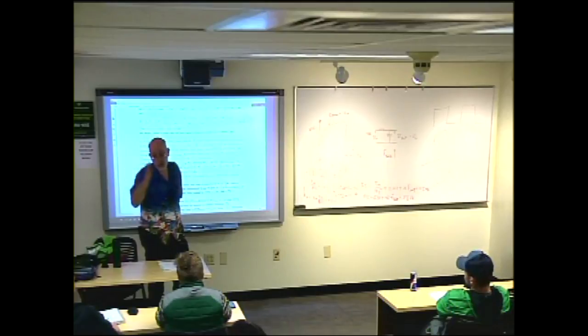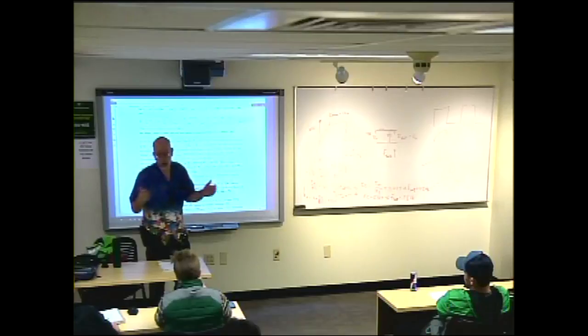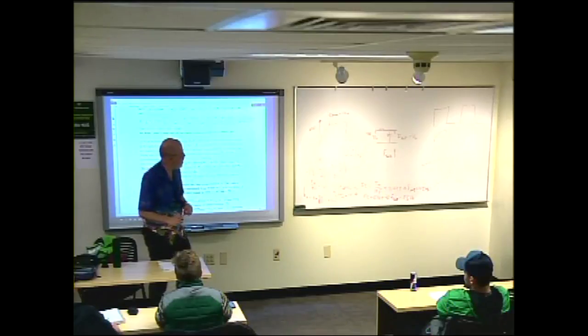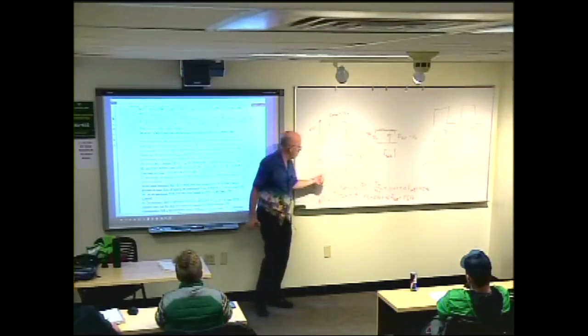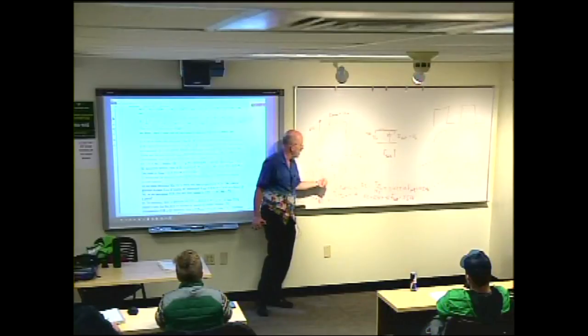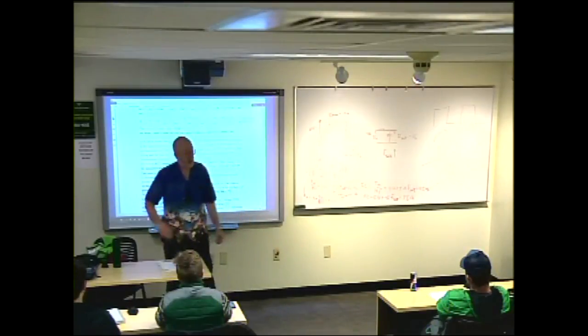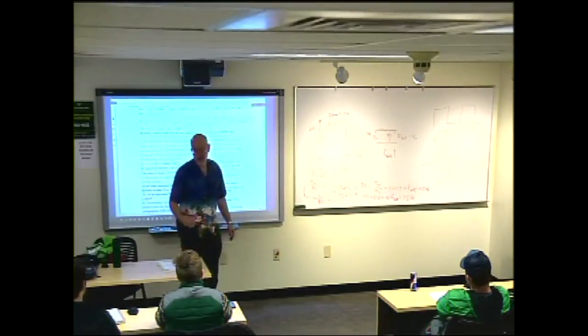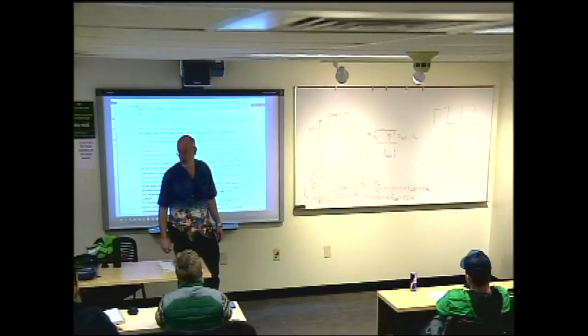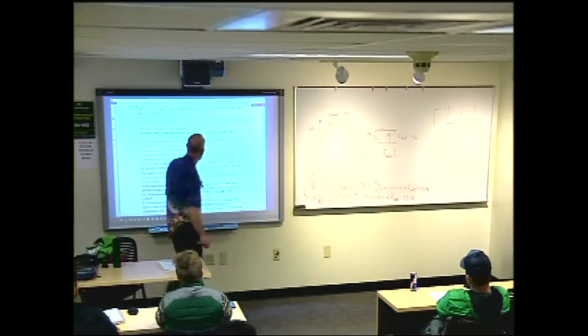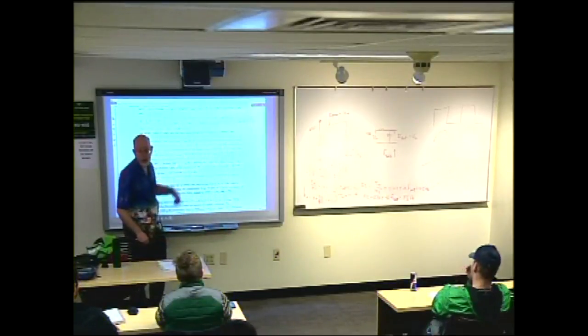It's kind of like running a filter right at the edge, where at the edge of a 3 dB filter, is there going to be any distortion to the waveform? Yeah, there's 3 dB worth of distortion right at the edge of it. And so that's why you wouldn't want to run a filter where tau n is less than RC. In fact, RC needs to be much less than tau n to make this work. And that's why the absolute value signs appeared here.